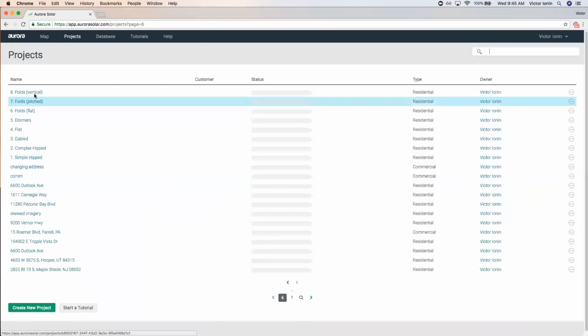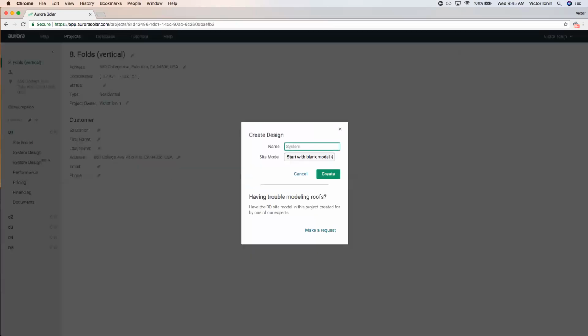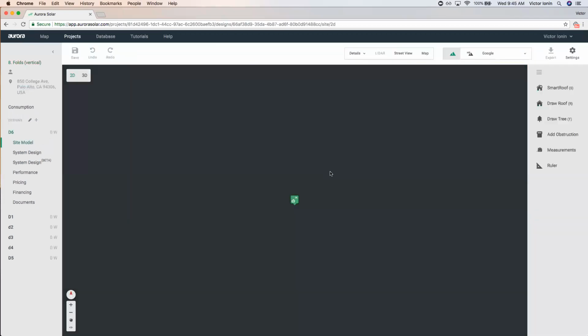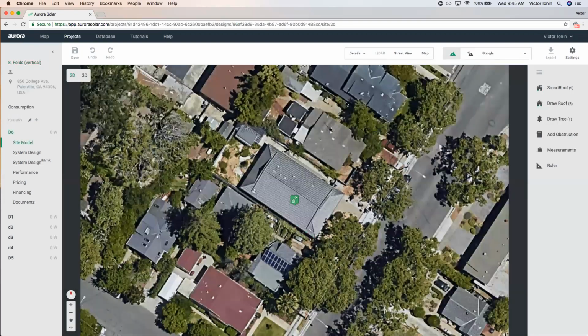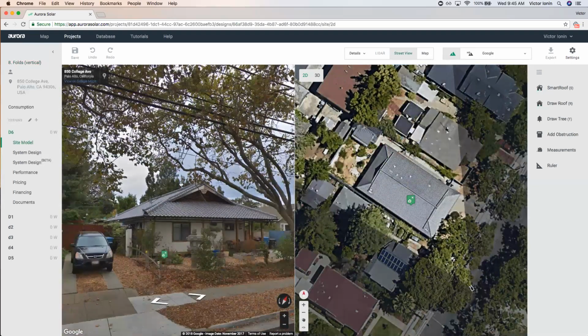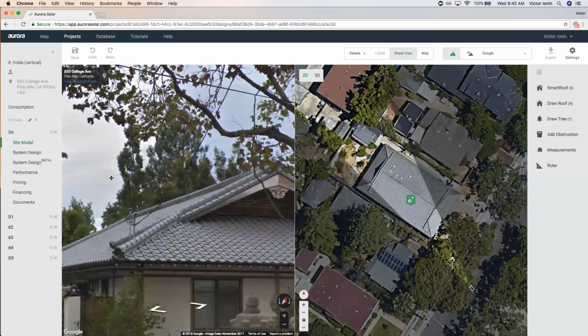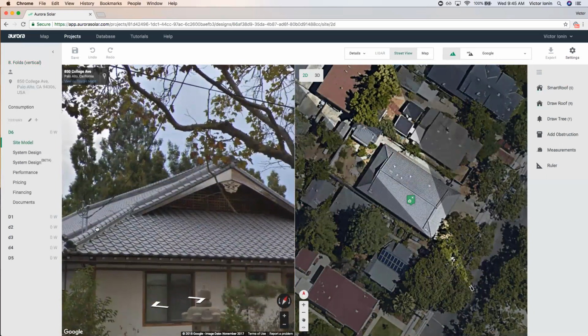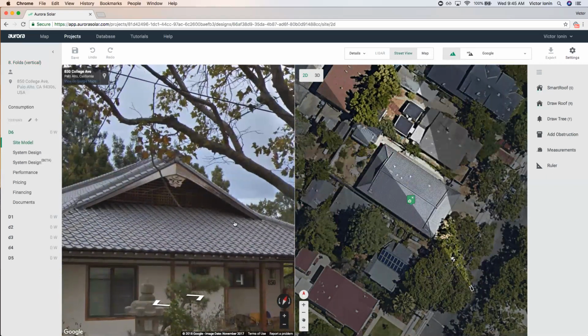Our last fold is called a vertical fold. And this one's used mostly for Dutch gable type structures. What you'll see is a structure that looks something like this, very similar to a standard hipped roof, except if you look at the hip lines, it goes up halfway and then it stops. Then it becomes like a side, like a rake, and it goes straight to the ridge instead of continuously going up at an angle. What that creates is a triangular, vertical wall piece.